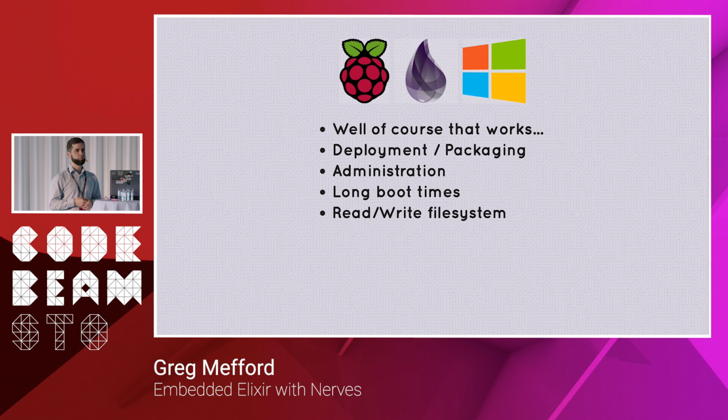It has relatively long boot times for an embedded device because it has to load up the entire operating system, or however much of the stripped-down operating system that you want to manage yourself. And then typically you also have a read-write file system, which becomes a problem if you suddenly pull the power on the device while it's writing to the hard drive. Then your file system's potentially corrupted, and then it won't boot next time, which would be a sad day.